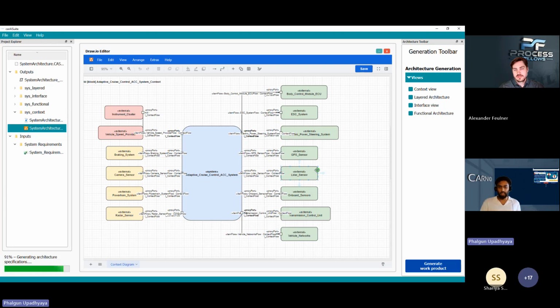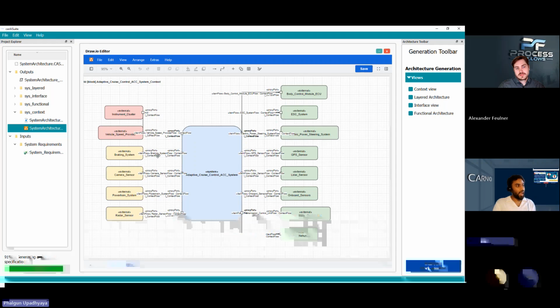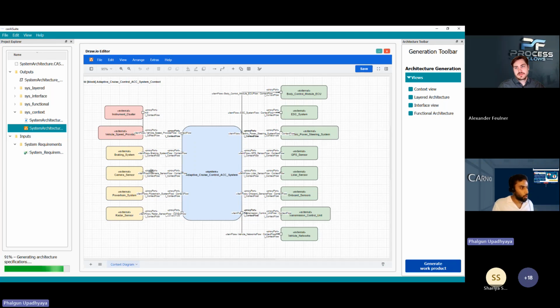When we are talking about the context diagram, you have different connections. In the requirements, we also saw there are many requirements regarding the activation and deactivation conditions, which means you would read a lot of different sensor data. So these are the different connections that are available. You can see that the tool identified each of these components along with the connections. It has the different connection mechanisms, so you can see the item flow direction and the different ports. Also, to answer your third point, Alex, we also have the SysML format incorporated, so the tool is able to generate it.